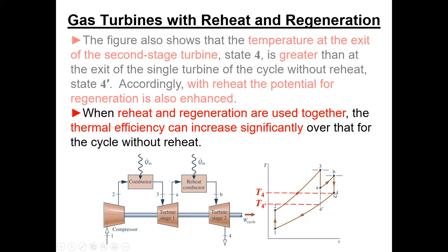So if you're going to do reheat, you're really going to want to do regeneration, because the reheat makes the regeneration more effective because you have a higher temperature coming out of your final turbine stage. So that's what that's looking at.